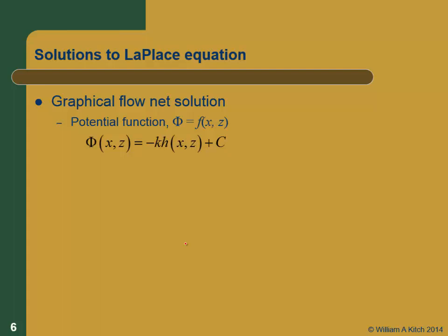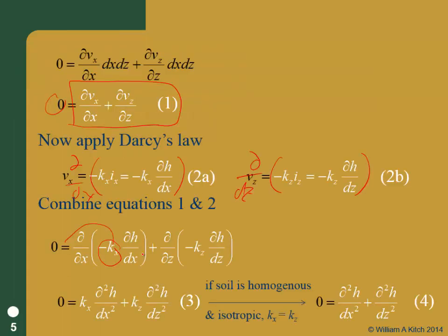Hydraulic head, the total head, not the velocity head, not the elevation head, the total head. That's what we were talking about here previously when we're talking about head. We're talking about the total head. Pressure does not drive flow, elevation does not drive flow, it's the two together. We're going to ignore the velocity head in soils because it's really, really, really small. So we can ignore the velocity head.